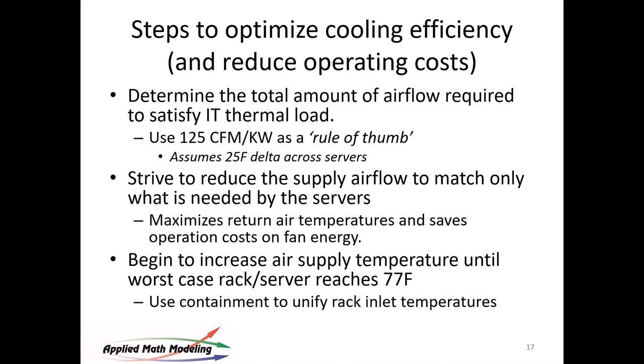And on air supply temp as well, there is a point where if you get too high, the servers will start to kick into overdrive on their thermal control system and ramp the fans up, and then you're losing. And that number that is often referenced is 77F. And I apologize to my international community who's all going, what is F? But we're in America and we use Fahrenheit. But right around 77, the thermal systems in the server start to ramp, and you begin to lose your advantage.